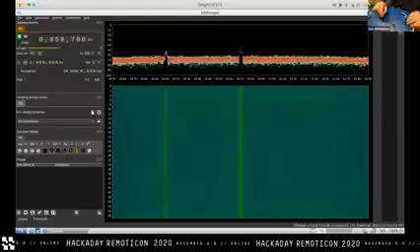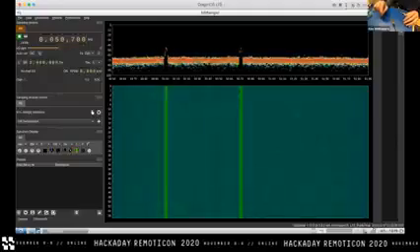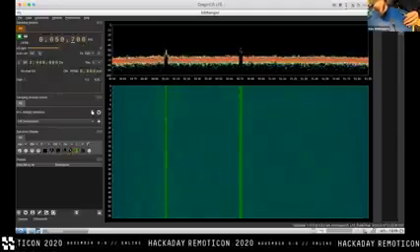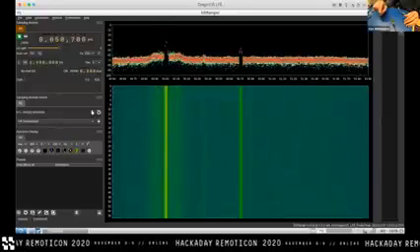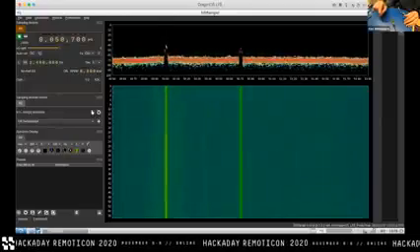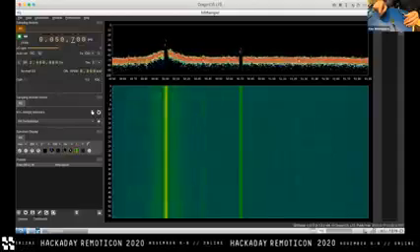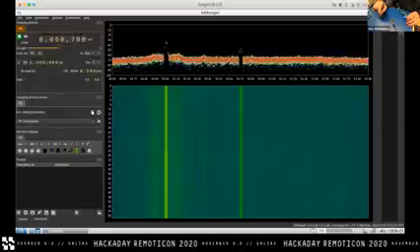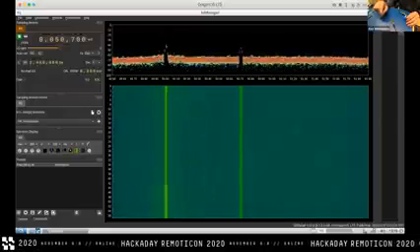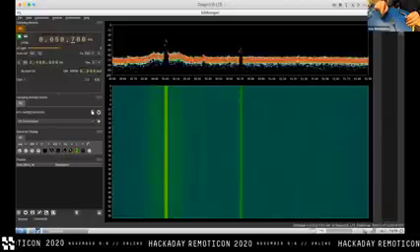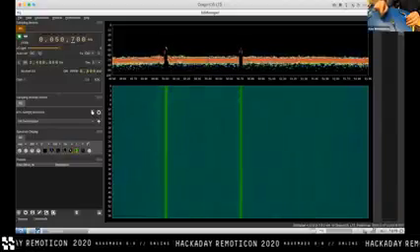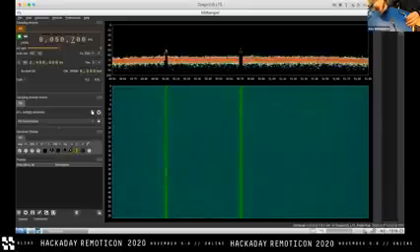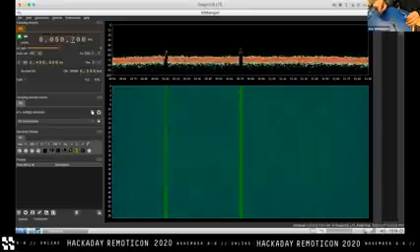We attach the big probe and start to try to look around where it might be. It looks like it's not down at this end of the board, but it's a little bit tough to say. It's getting hotter over here. That's interesting. Okay, so it's getting kind of hot in this area of the board, like centered over the BX. If we move over to the other side, it's still pretty hot. I don't know. It's definitely somewhere up on that top half of the board and definitely less obvious down here. Definitely not the far corner of the board.